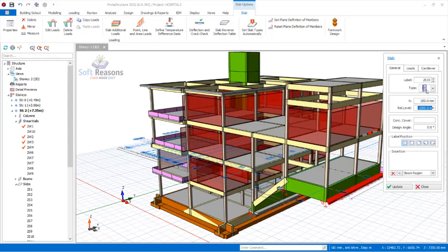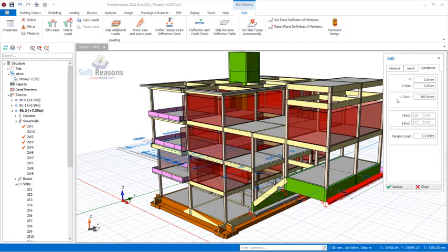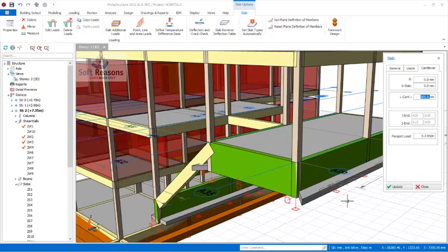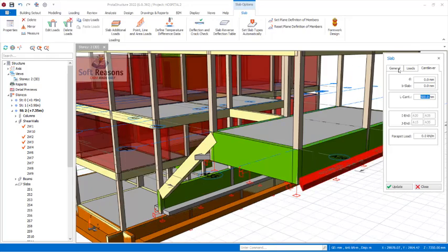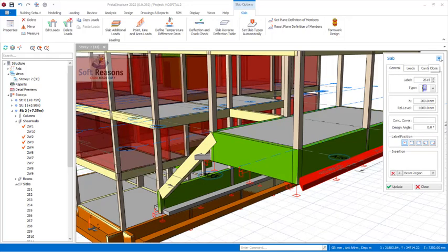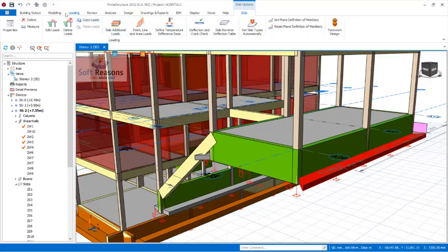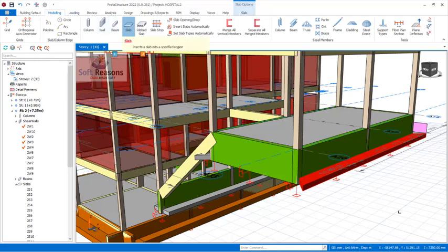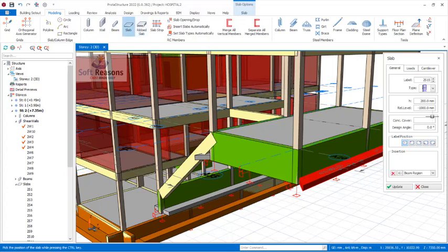That cantilever slab will now act as a support at the base of the shear wall. Now if you come over here, you can key in the L count, which is 500 right there, which is this extension you see is 500. Now what you normally do, the slab thickness is 200. For instance, if I get back to the modeling tab and then click select slab right there, in the slab dialog you can see the settings here. The slab type, you have to select it right there.